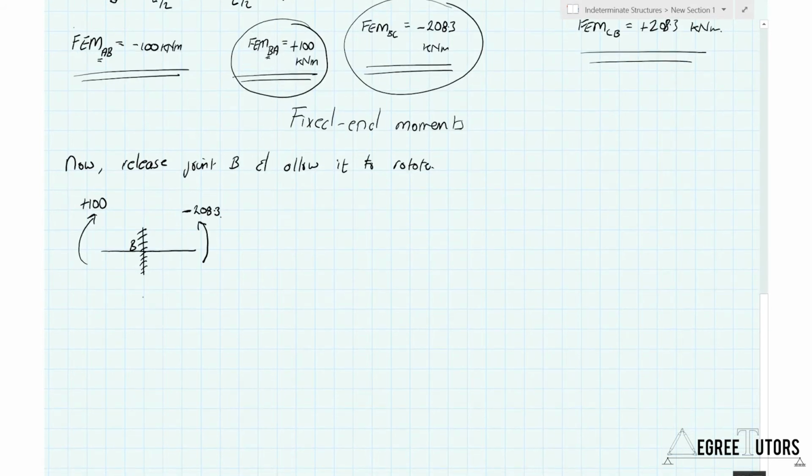Right. Now, if I was to consider what would the bending moment diagram at that joint look like, it would look something like this, right? We would have a moment coming up. That would be for the left-hand side, but then on the right-hand side, we'd have a moment coming up to a higher peak. Now, this is not a valid bending moment diagram. You're not going to see a step in the bending moment diagram like that at a joint here, where only two members are coming in to meet at the joint.